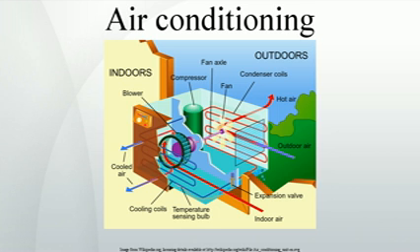Absorption heat pumps are actually a kind of air source heat pump, but they do not depend on electricity to power them. Instead, gas, solar power, or heated water is used as a main power source. Additionally, refrigerant is not used at all in the process. An absorption pump absorbs ammonia into water. Next, the water and ammonia mixture is depressurized to induce boiling, and the ammonia is boiled off, resulting in cooling.